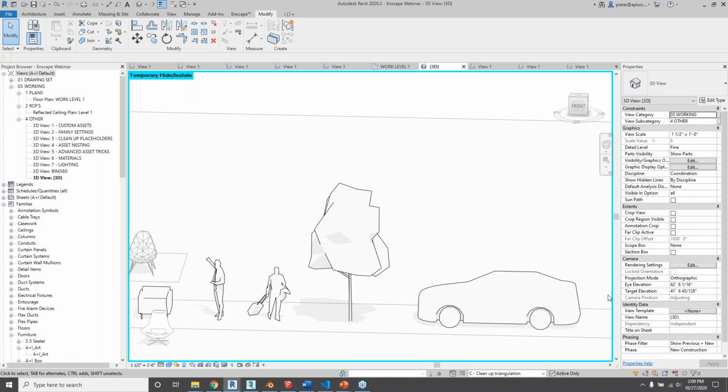Okay, I think we're just going to do a couple more questions here as we're coming up to the end. Is there a way to only have plants show in a color, for example green, in a white mode setting? No, I wish there was. V-Ray had this list of materials to exclude from overwrite. That is really useful, because then you could choose what you want to white out, and still have some accent materials that you can play with. Right now, white mode is a total blanket white mode, except for anything that's transparent and water, I believe.